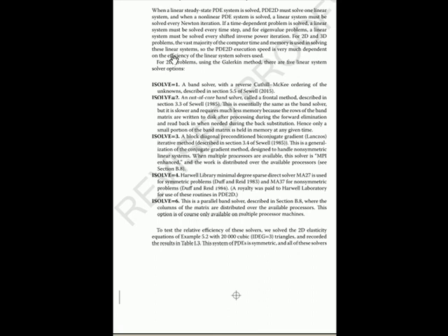It has some sparse direct solvers and iterative methods. The sparse direct solvers are the workhorses. Those are the ones you should normally choose. It also has some parallel solvers which will run efficiently on a multiprocessor machine, which you're going to be using for some or most of your problems, so you may use this also.